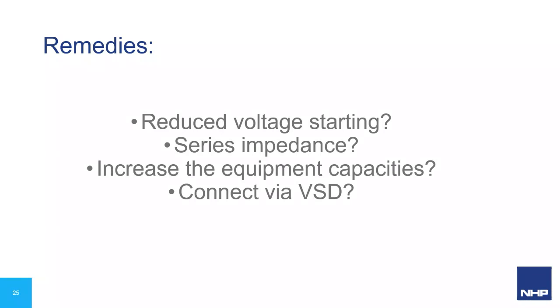In many applications, the torque produced by the motor may be marginal in accelerating a load on DOL anyway. If we use a star delta voltage reduction method, 58% of the voltage in star connection, the torque will be reduced by the square of the voltage reduction to roughly 30% of the torque availability. The same is true of electronic soft starters.